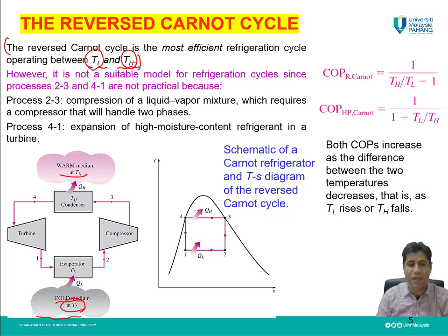refrigerator. Then it goes to the compressor, which compresses the gas. As you know, in the evaporator the liquid changes phase from liquid to vapor. It goes to the compressor, and again we will have a high pressure fluid with high temperature.